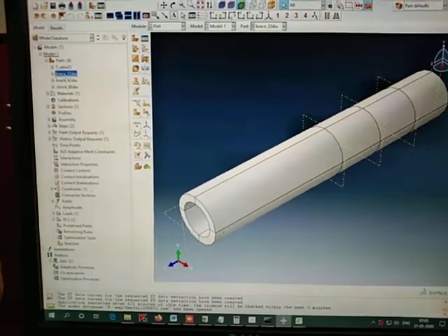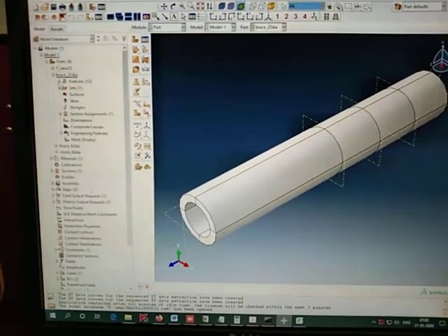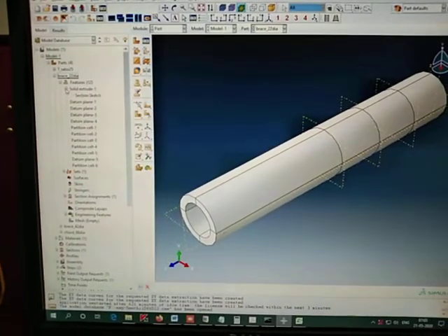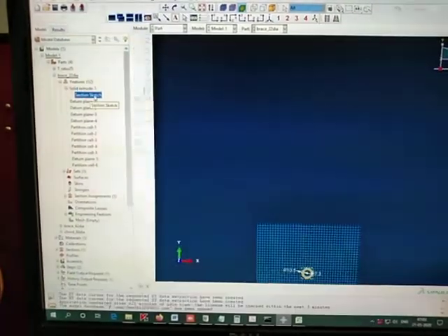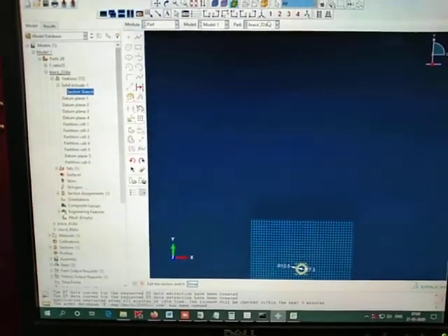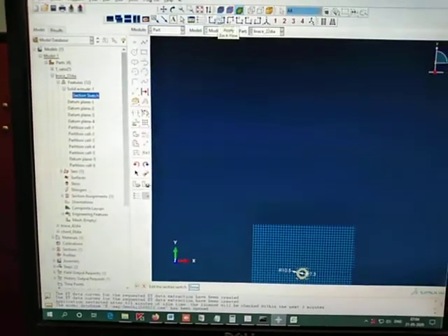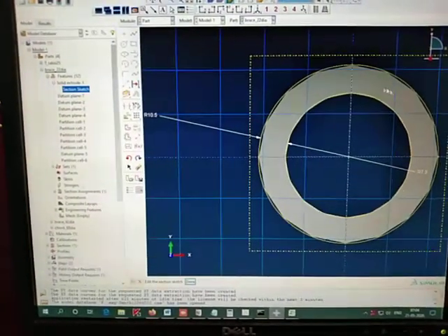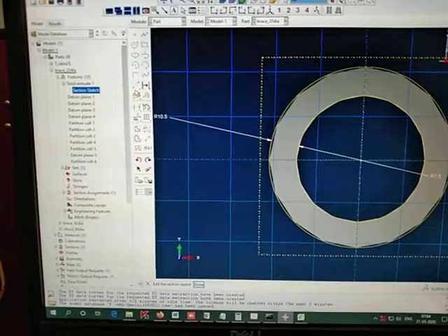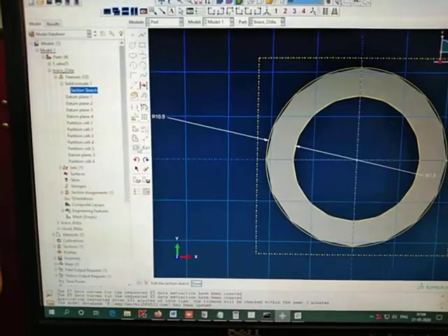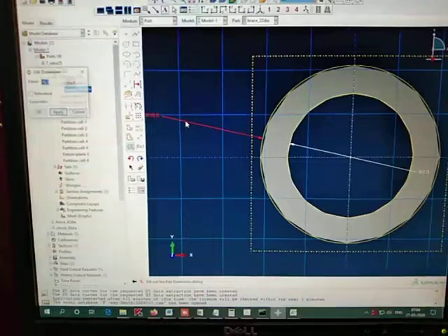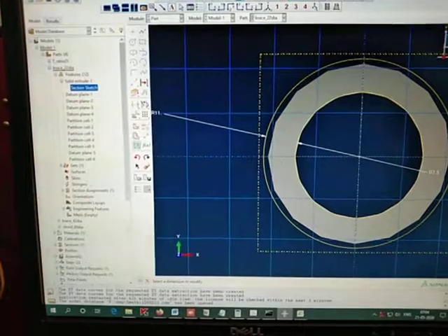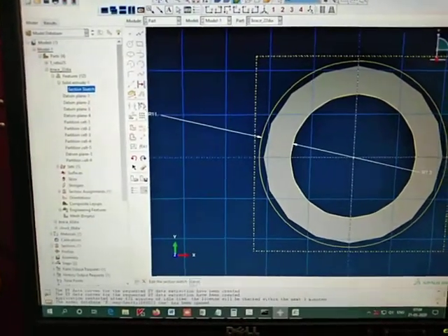So in this, how to create or edit this brace: under this option you can have this solid. Under the solid extrude we will have this section sketch, where you can edit it for the required diameter, outside and inside diameters. Then see here there are options for changing the dimensions which I have given. Instead of 10.5 I can give 11. So without any further delay we will go for the properties.